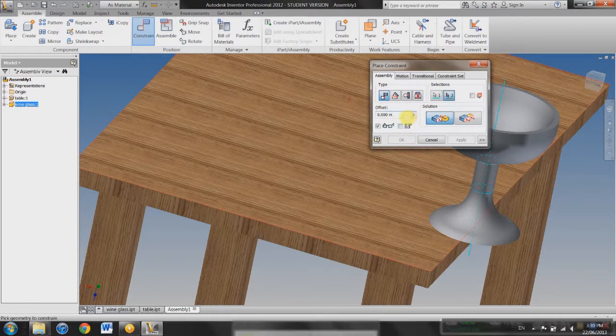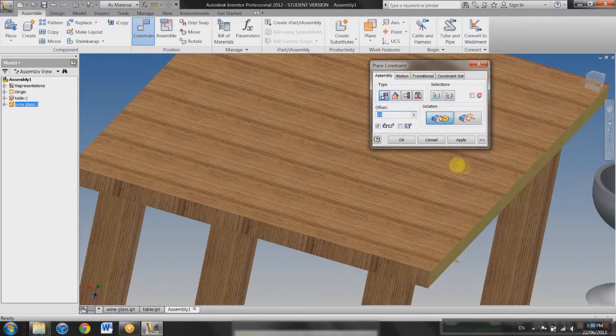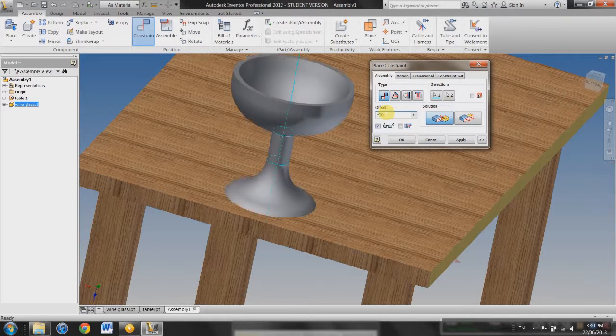So you're going to go to your offset tool and hit, say, 10. Not 0, 10. So if it goes in the wrong direction, just press -10 and it'll shoot onto the table. So perfect, it's on the table. Hit apply.